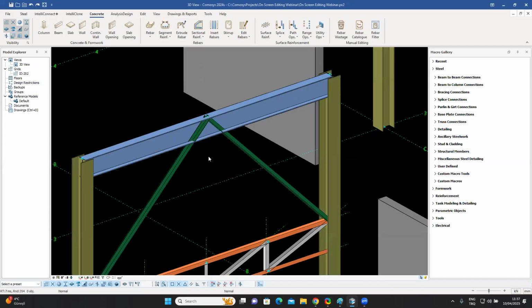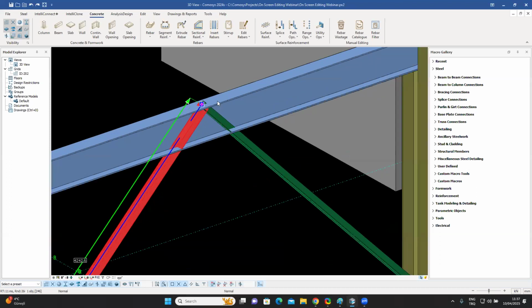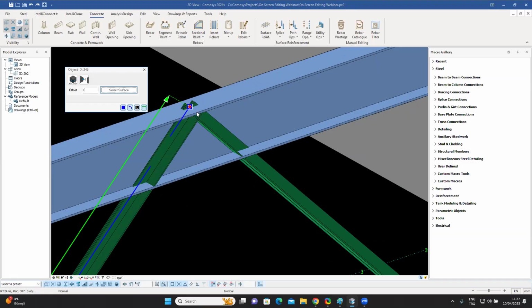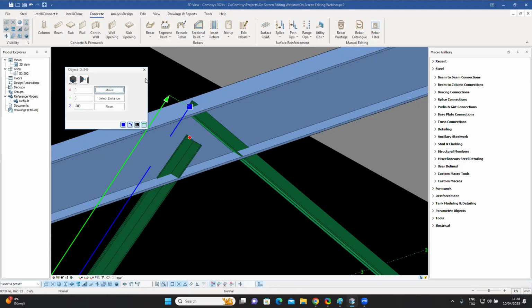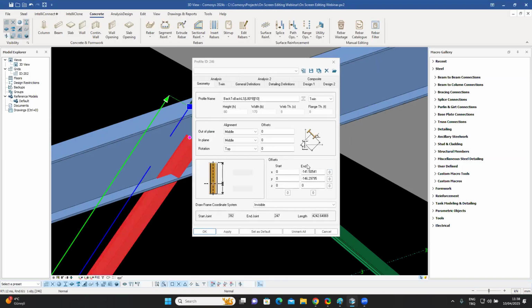to a desired location. Now for that, for example, if I select this one, if you remember, I chose the tail over here. But instead of the tail, if I go inside and select this one, the little circle inside over there, and now give it a distance of, for example, minus 200 in the Z direction, and if I say move, you can see that my frame element is still connected to the top, but the physical element has been given an offset. And this appears in the form of these numbers, which are difficult to calculate otherwise.